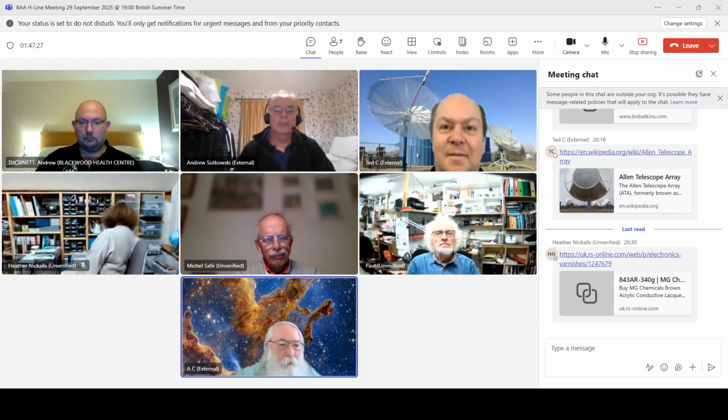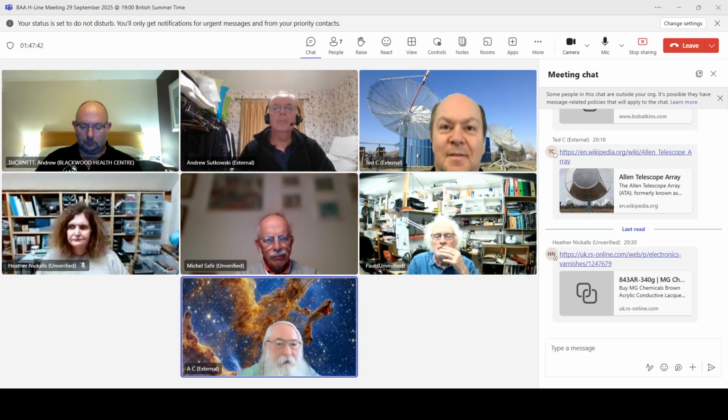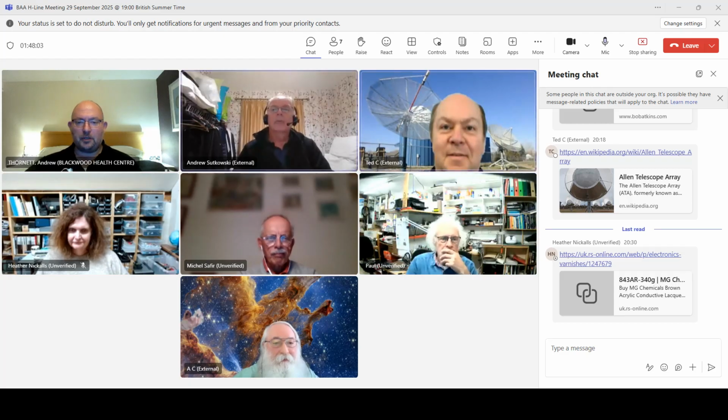If you're pointing up and you've got that antenna pointing down by itself, a lot of those side lobes really generate significant signal from ground noise. And so when you add those choke rings, it really brings that whole effective area into the reflection out of the dish. So yeah, that's fantastic. That 3D printing could really simplify the manufacturing for sure. Yeah, great work, Andrew. Thank you very much. That's marvellous.